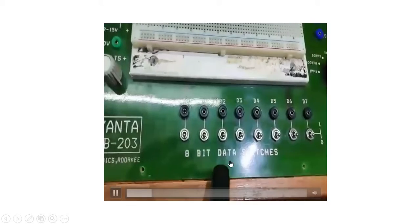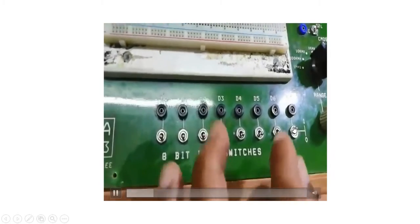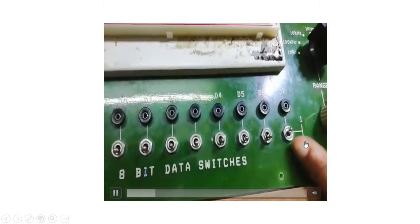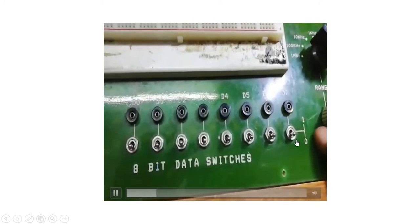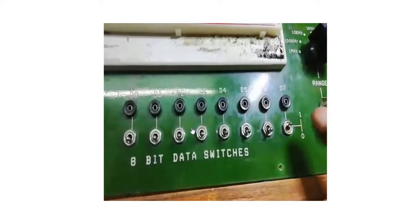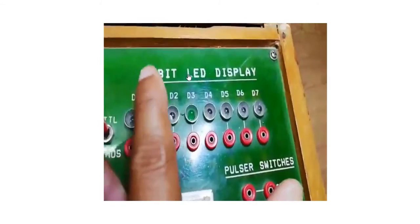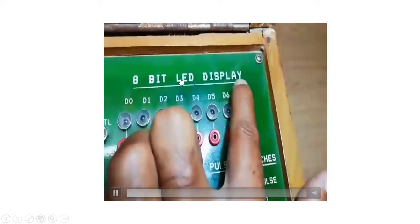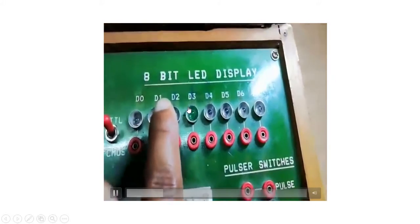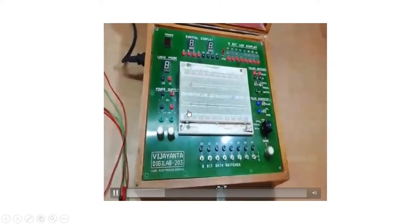Now this is 8-bit data switches which you can use to give the input. When you make the switch on, it will give logic high, and when you make it off, it will give logic 0. So these 8-bit data switches you can use as input. Now this is the 8-bit LED display. You can use this to show the status of output. If any of these LEDs glow, that means it shows logic high. Otherwise, if it is off, that means the output is logic 0.